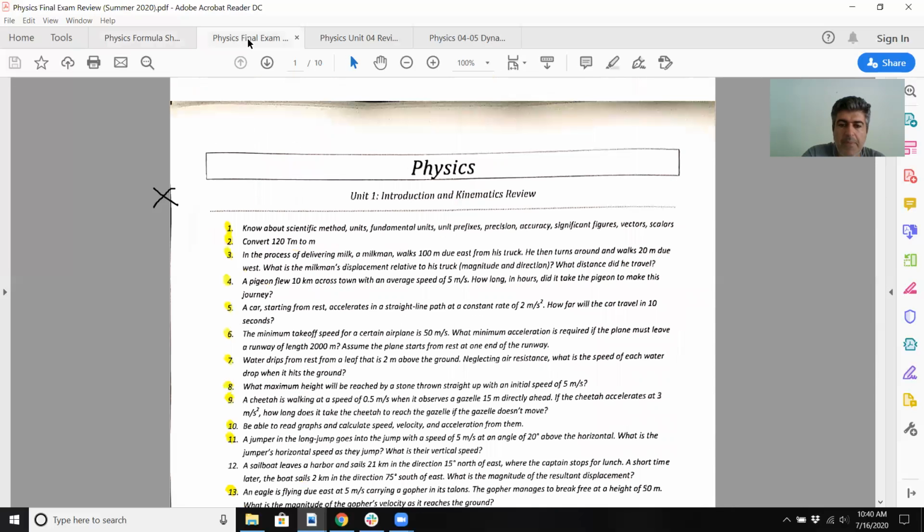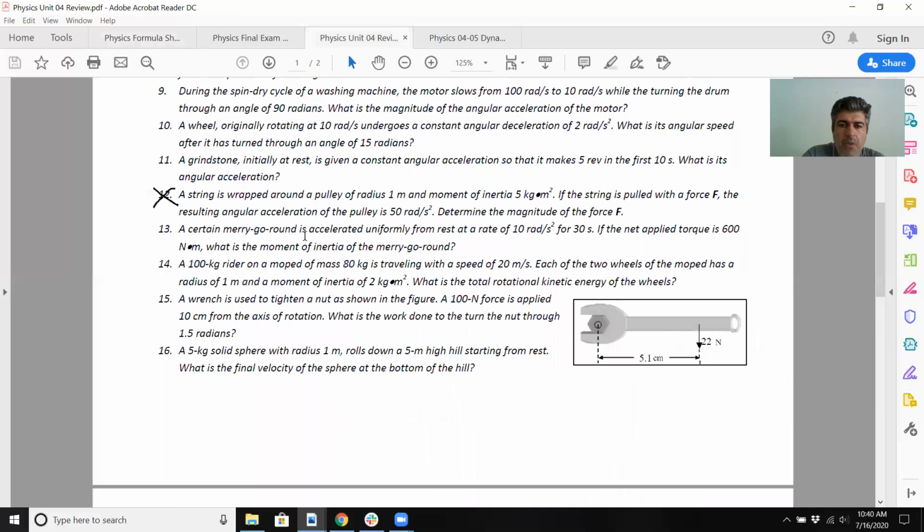So yeah, that's a fair problem, because we have talked about torque being I alpha, and you have your alpha, obviously, is 10, and you want the inertia. So the rest of the stuff actually was kind of useless. You didn't even really need the 30 seconds. I think what I probably would do is make you find the acceleration and then plug into the I alpha formula and then solve for I. But again, torque, which is given to you, equals I, which is what we're trying to find, times alpha, which is given right there. So perhaps the answer is going to be 60 for that one.